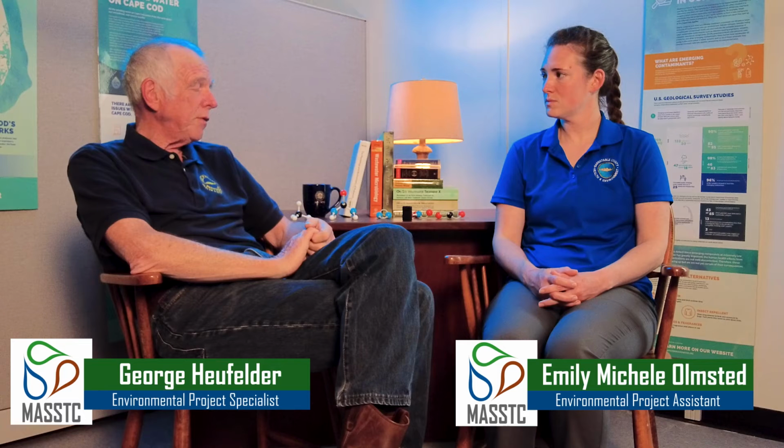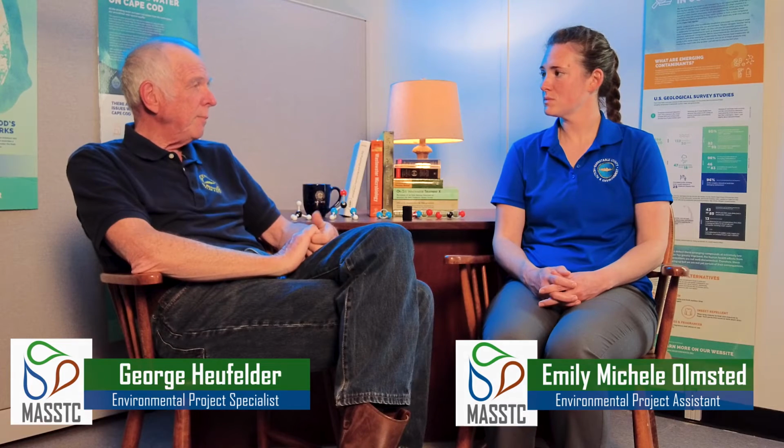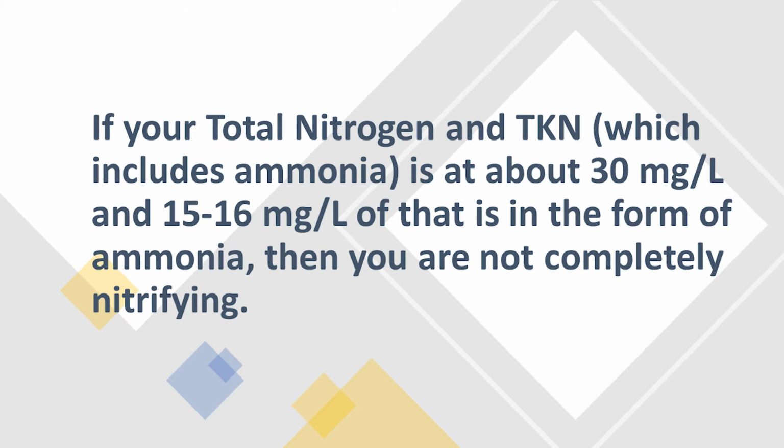And many times we find that is the problem with some of the systems that aren't denitrifying because they can't nitrify. You'd get a key to that in your discharge because you'd see a lot of ammonia. If your total nitrogen comes out in your TKN, which includes ammonia, remember, if you're coming out at, say, a 30 total nitrogen and 15 or 16 of that is ammonia, then you know you're not nitrifying completely.